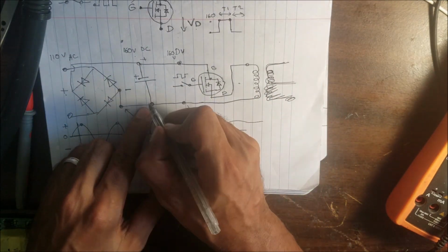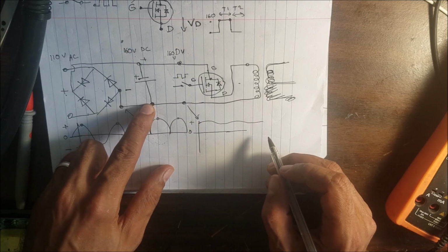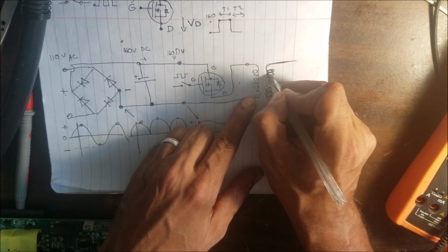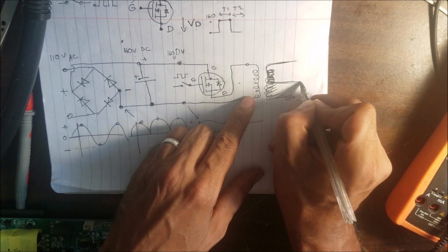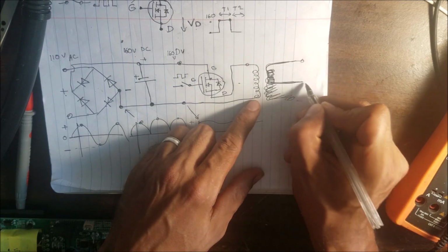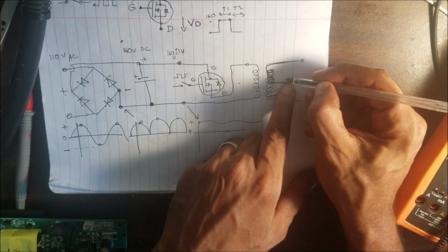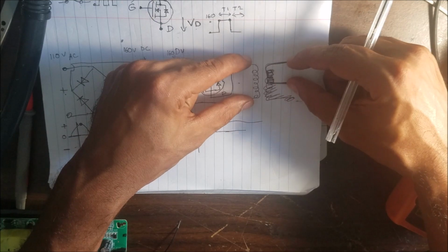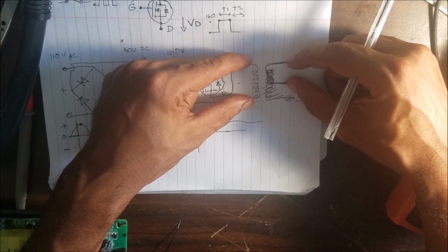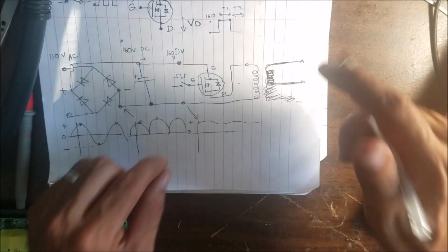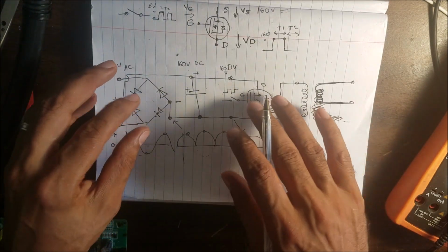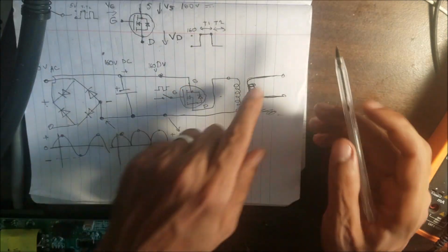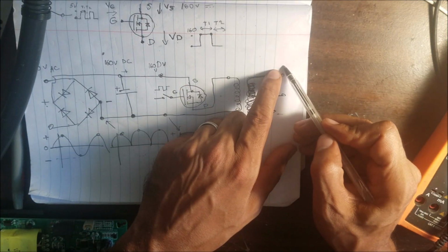The other side of the transformer is going to connect to the negative side of the capacitor, and that's the primary, and we're going to have a secondary side of the transformer. So I make this coil small just for you to know the size. If we have a big voltage here, the transformer is going to transfer it to a small voltage here. We said at the first we want 110 volt AC to become a 5 volt DC.